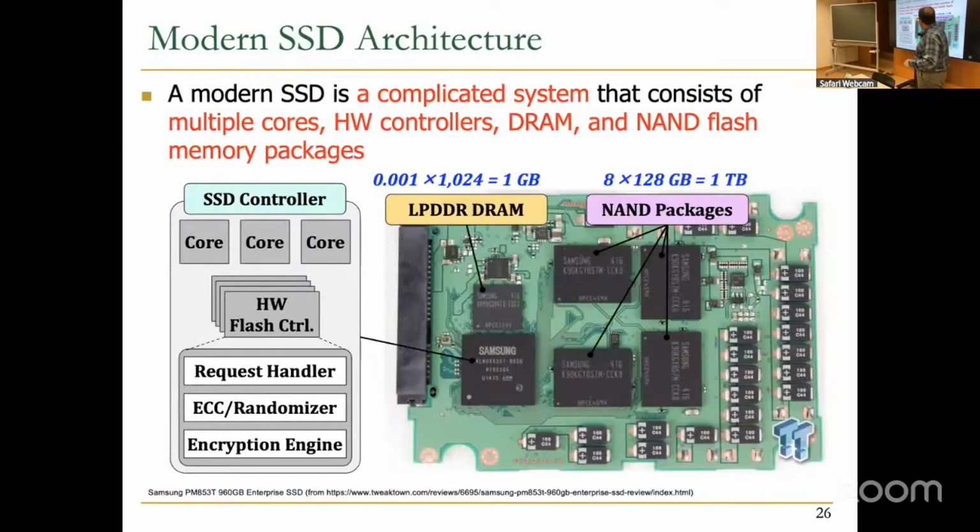Inside the SSD controller, we're going to see more. Essentially, you have several cores and some hardware flash controllers, and these flash controllers do a lot of the controlling logic that we need in order to communicate with flash memory. Compared to memory controllers for DRAM, which we argued a lot during this course need to be more intelligent, current memory controllers are unfortunately not that intelligent and not doing much, except what requires signaling to connect to the DRAM.